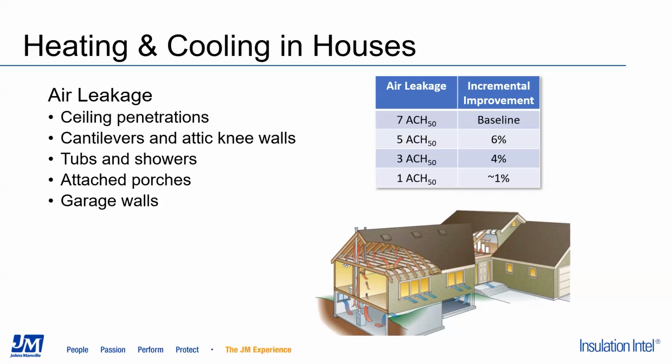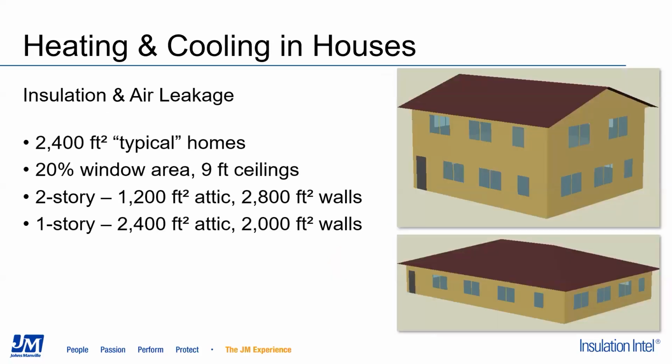And also one thing to keep in mind, the savings that I've got here are from some energy calculations that I did on a typical new home in the Atlanta area, so climate zone 3. If we were to put that same house in a colder climate like Minnesota, we might see these numbers be a little bit higher just because of the cold climate effect. More energy being used for heating, and air leakage becomes more important.